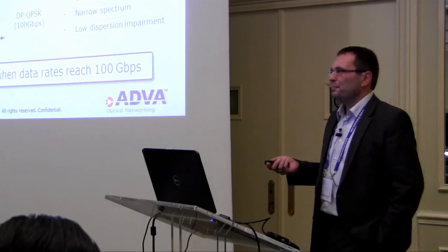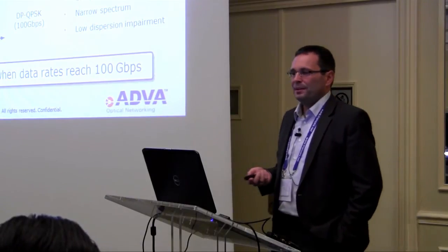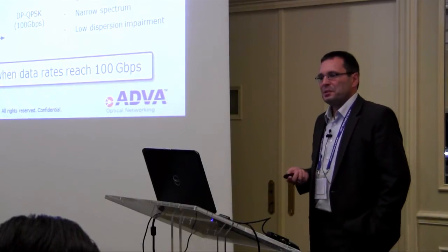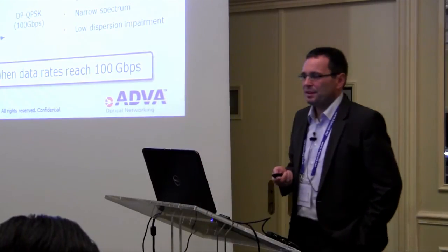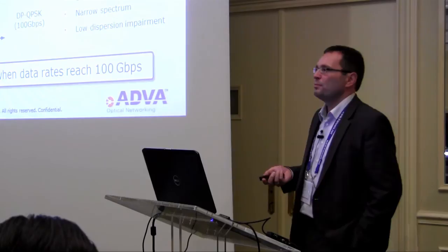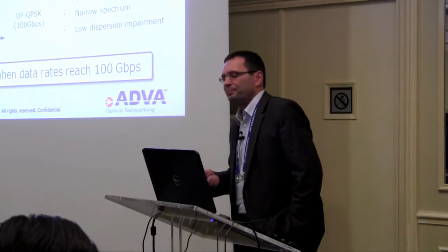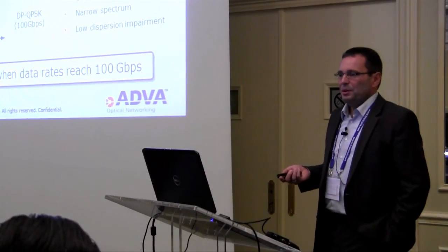On-off keying was used in the past because it's simple hardware. It's wide spectrum. Yes, there's a little bit of drawback there compared to newer technologies, high dispersion impairment, but this was solved by using dispersion compensated fiber. Now, what can we do in order to make this work?